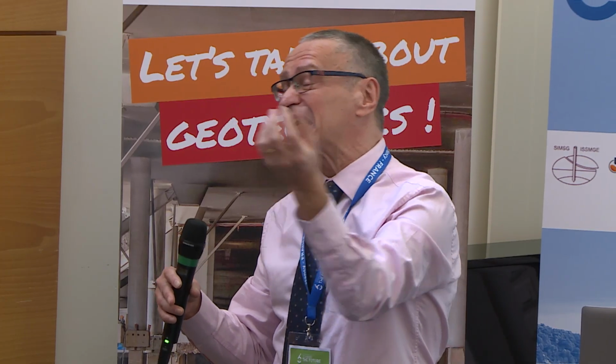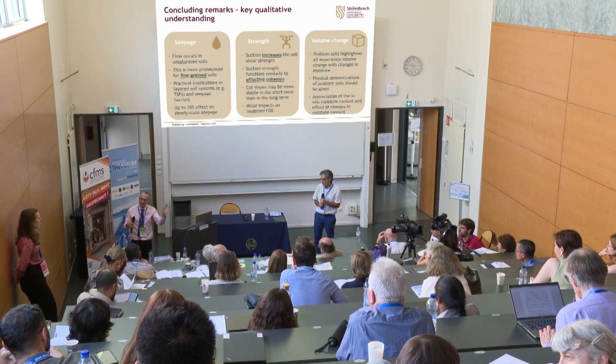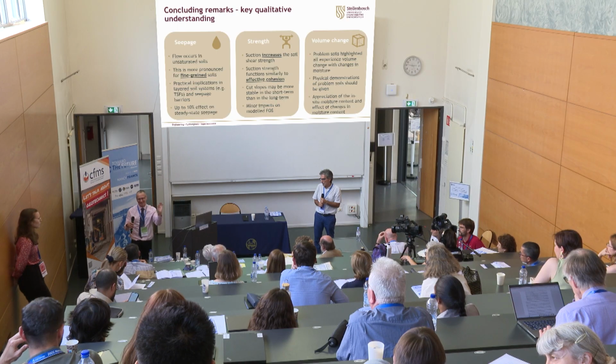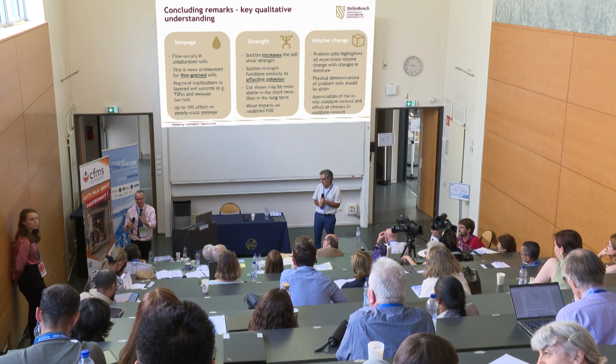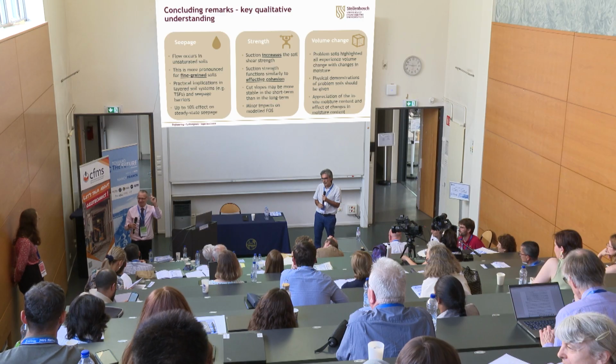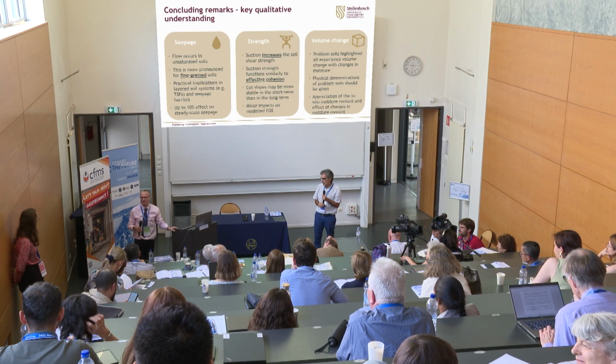And next time, you and me, instead of developing an ideal slope, will prepare a case inspired by the problem that they have. I don't want to have anything except a grain size distribution at least. And if it is a clay soil, a plastic limit, and then we can move from there. I'm not asking for a full set of experimental tests with all saturated and unsaturated parameters.